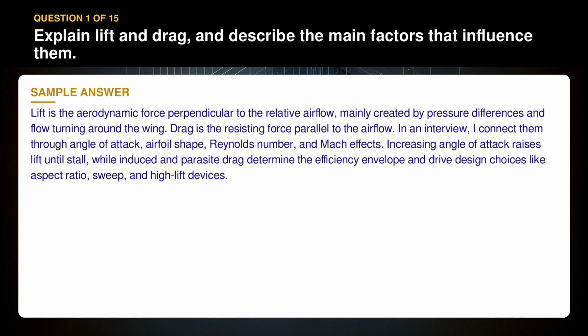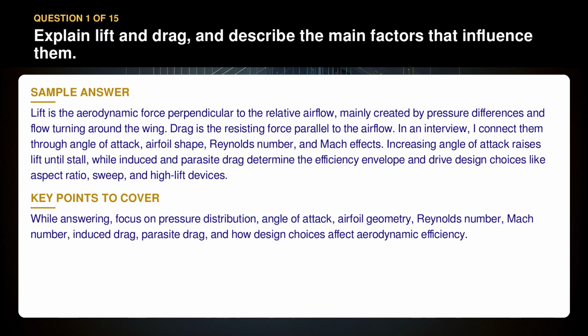Increasing angle of attack raises lift until stall, while induced and parasite drag determine the efficiency envelope and drive design choices like aspect ratio, sweep, and high lift devices. While answering, focus on pressure distribution, angle of attack, airfoil geometry, Reynolds number, Mach number, induced drag, parasite drag, and how design choices affect aerodynamic efficiency.